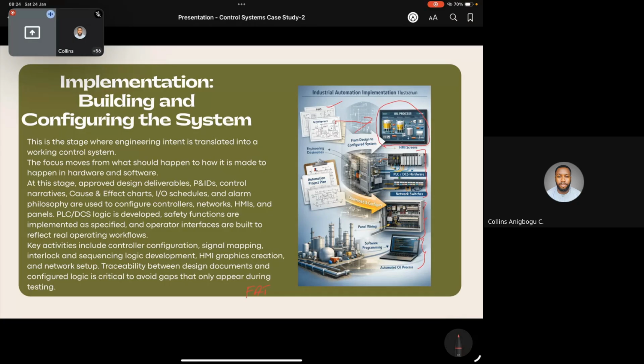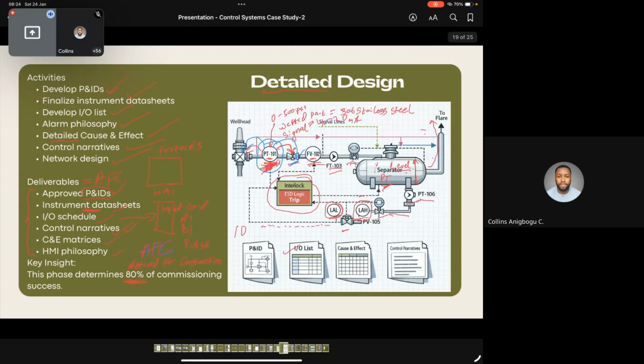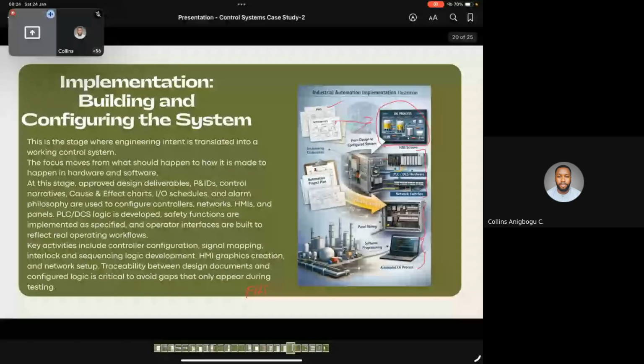You do your factory acceptance test. Essentially, the factory acceptance test will test against all the documents you generate. I mean, part of the documents you generated in detailed design is your FAT checklist, right? Before you even do your construction, you generated documents you have to validate. So you do your FAT, and then you ship the items to the customer site, right?